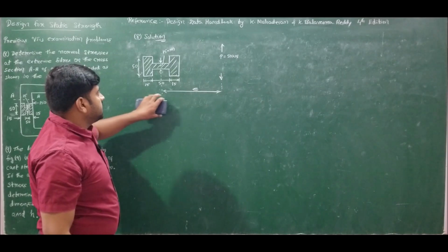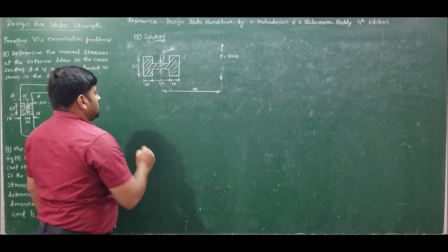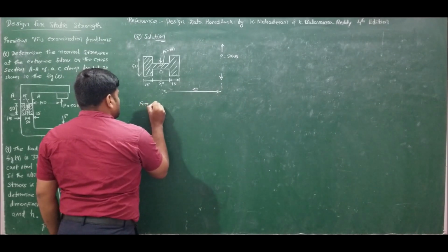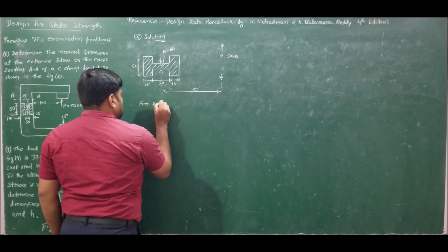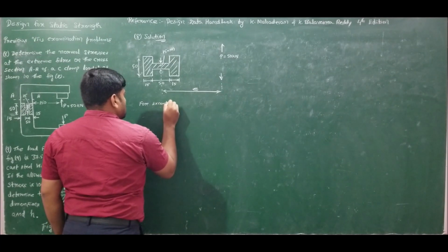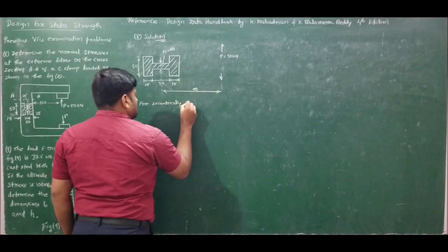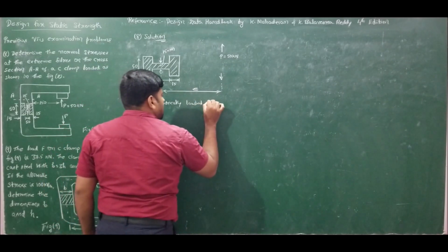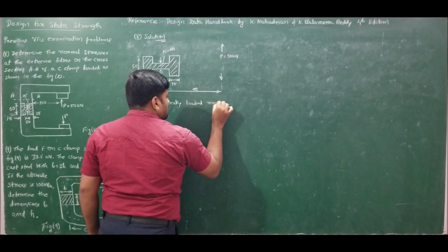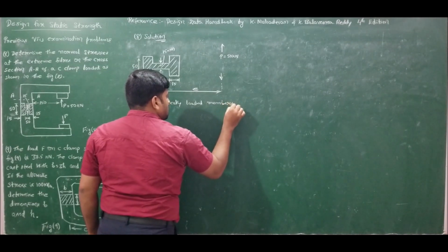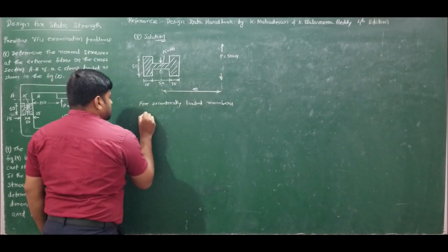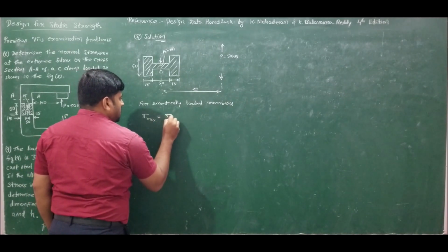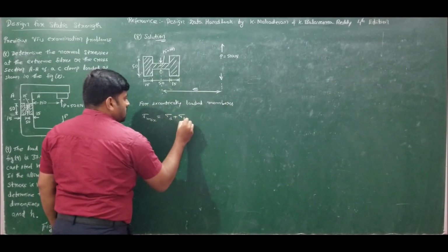Since this is an eccentrically loaded problem, for eccentrically loaded members, the maximum stress sigma max is given by sigma direct plus sigma bending.